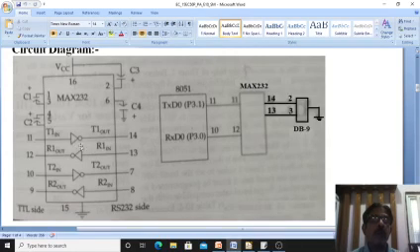For that I use an IC called MAX232. MAX232 converts TTL to RS232 or RS232 to TTL voltage levels, so that I can use serial data communication efficiently. So this is the brief on serial data communication and the requirement of MAX232. DB9 is required to connect from the microcontroller's MAX232 to your computer or any other external device. This DB9 9 pin connector is required.